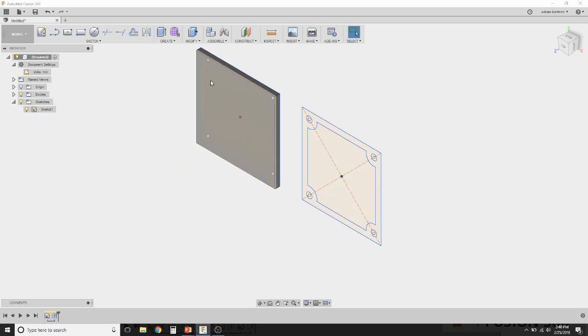Now, the next thing we're going to need to do is grab the area that represents the walls on our sketch and pull that through the base in order to get that where we need it to be. But no matter what I do, I can't really click on it. So what we're going to want to do is similar to what we did with the sketch. We're going to click the triangle next to the bodies.